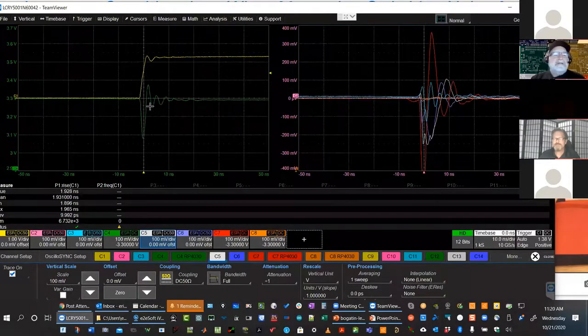And here he is. So here's our 3.3 volts. When the IO switch, and we get a lot of current drawing, look, this is that switching noise signature. And the rail probe is automatically adjusted with 50 ohm impedance at high frequency, high impedance at low frequency. And so this is not ringing, this is the real voltage noise on the die itself.